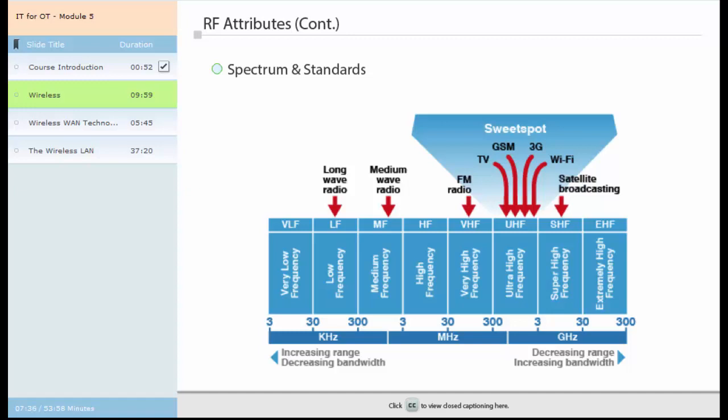The cellular service utilizes different frequencies for different parts of the service. Some are used for voice, some are used for data, and others for both voice and data services. Both microwave and satellite transmissions take place in the 3 to 30 GHz frequency range. However, unlike Wi-Fi, these technologies operate in narrow frequency bands that are strictly licensed and controlled by the FCC and the ITU. These technologies are also used for voice and data as well as network backhaul systems.